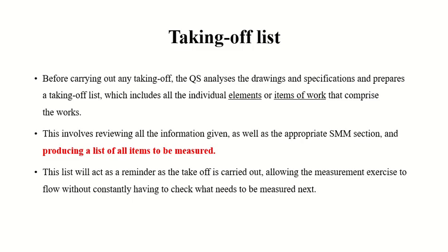And once this is done, you will prepare a list of items for which you will do the quantities, for which you will do the taking off. And when you are preparing this list, you have to have a copy of the SMM with you, the type of SMM which you are applying in your country, because your list must match with the items in the SMM.